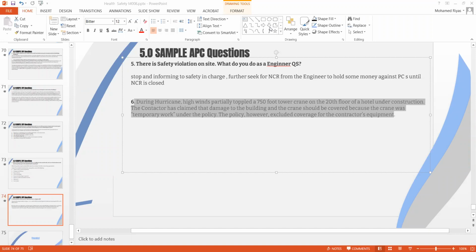Clauses 70.1 and 70.2 deal with subsequent legislation. If the authority is insisting on certain proactive measures which need to be taken care of, additional cost can be claimed under 70.1 and 70.2, and the additional time can be claimed under special circumstance. Again, it depends on your contractual amendments. If there is any modification to that, it will be dealt with accordingly. But there is a possibility you can use 70.1 and 70.2 for the cost part, and for the time part you can use special circumstance.